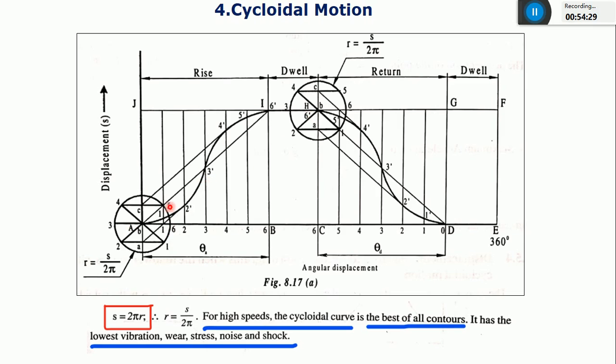After that, if you are getting this smooth displacement curve, then that particular type of motion is called a cycloidal motion. It means it is an optimized motion of all the different varieties of follower motion. It is not having a uniform velocity, it is not having a uniform acceleration and retardation, but it is having a combination of all the optimized patterns.